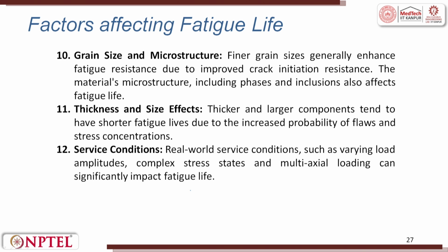The grain size and the microstructure. Fine grain size generally enhances the fatigue resistance due to improved crack initiation resistance. So that's why we always try to quench the sample and do other things, right? Grain size refinement. The thickness or the size effect. Thicker and larger components tend to have shorter fatigue life due to the increased probability of flaws and stress concentrations. The service conditions also play an important role in the fatigue life. Real world service conditions such as varying load amplitude, complex stress states and multiaxial loading can significantly affect the fatigue life.